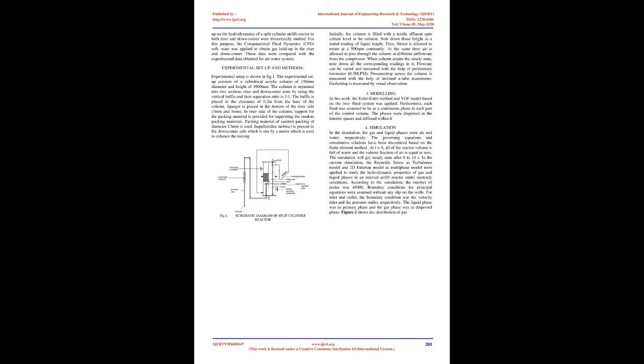At the higher viscosity values, the higher rate of bubble coalescence has been reported as responsible for the observed decrease in gas holdup with increase in liquid viscosity. Mass transfer performance and mixing rate are affected by reactor geometry, which depends on several other parameters such as the height to diameter ratio of the vessel, the cross-sectional area ratio of riser to downcomer, and gas-liquid separator design. In recent days, many researchers carried out their study on hydrodynamic and mass transfer